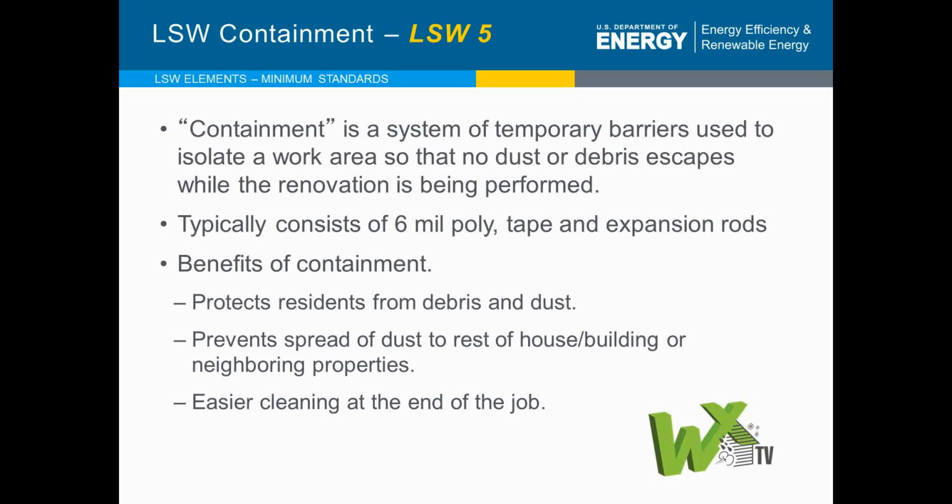And we need to contain that area so dust doesn't drift out of that area and get into clean areas. Typically when we talk about containment by way of materials, we're talking about polyethylene, a minimum of 4 mils, preferably 6 mils, because we have to clean that. We have to clean that plastic by vacuuming and wet cleaning, and if you've ever tried to vacuum anything less than 4 mil with a vac, it ain't going to happen. 6 mil is very, very common.